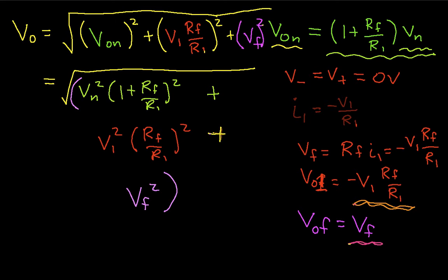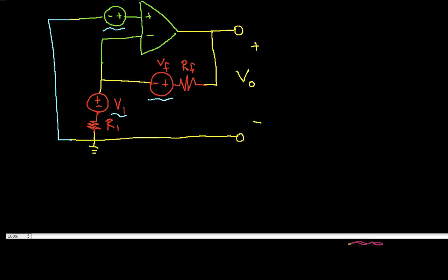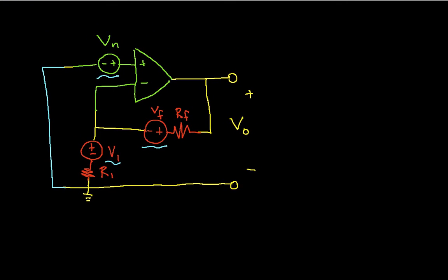So at that point, we'll pretty much call this finished. What I would like to do is just recap the process to make this hopefully clear in terms of what we've done. In order to determine the noise power at the output, we have shorted the input of the amplifier circuit to ground, because we don't want to know what the response of the circuit to an input signal will be. We want to know only what the noises internal to the circuit are doing to it.